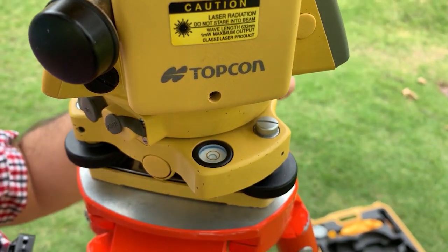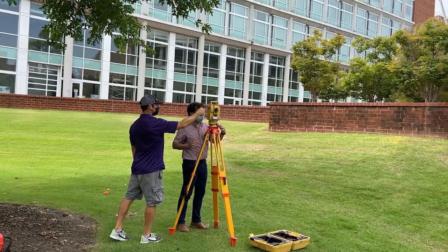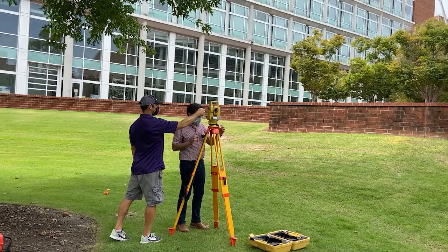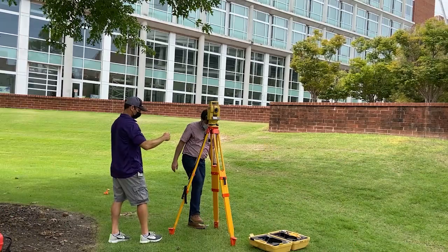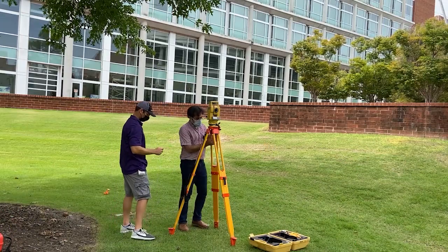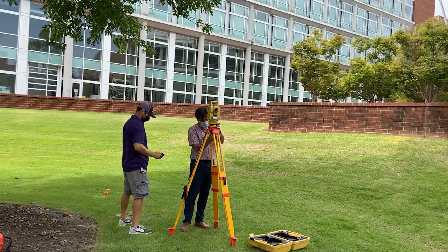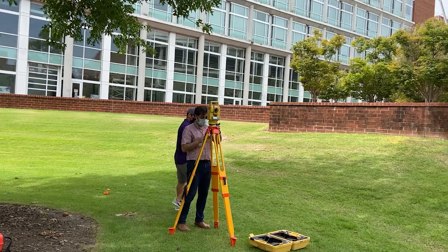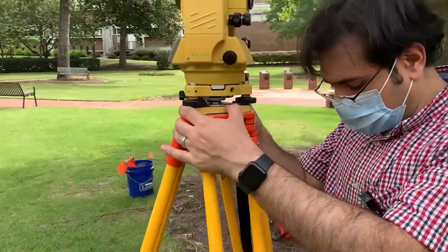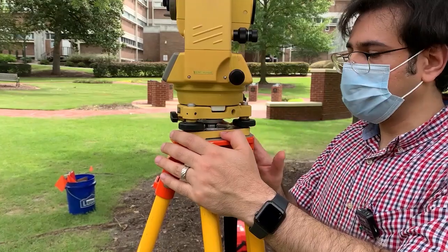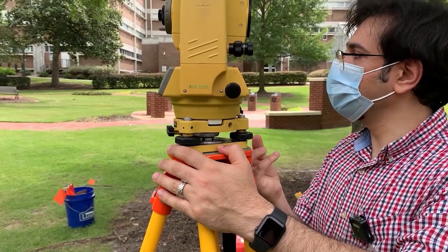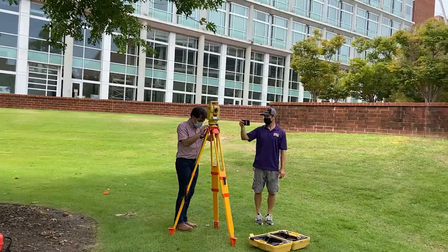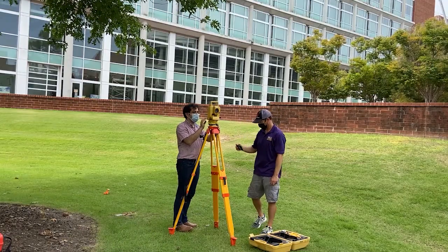At this point, you grab the 3rd one and you make it right in the center. By doing this, now your point might be a little bit off the point. That's the step that you need to unscrew this total station and move it slightly. That's what I said. You need to make sure when you set it up, it's in the center of the top of the tripod. If it is not, then you would not be able to move it.